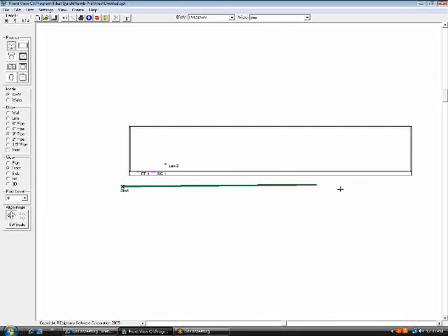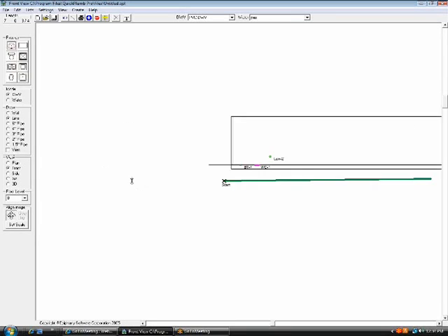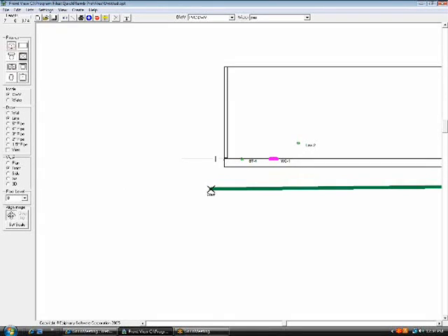It will be a 1/8 inch per foot fall. Okay. And you can see the pipe here in this window. In the front view, you can see that slope. And let me show you the 36 inches that we used when we drew that pipe. That represents this distance here.